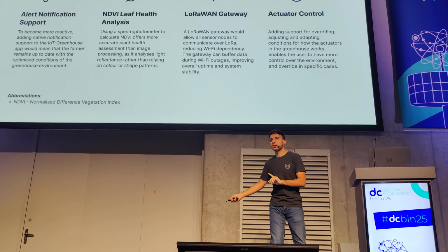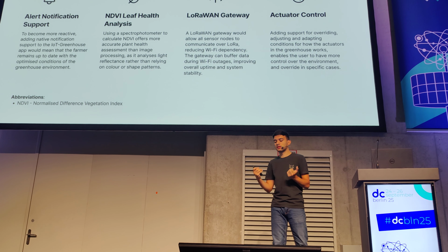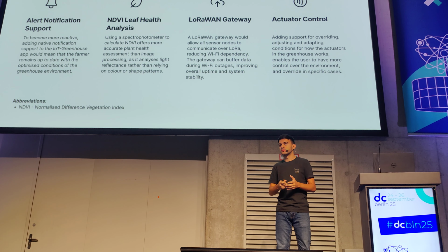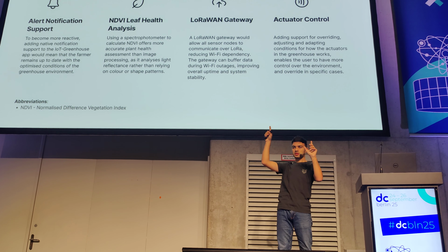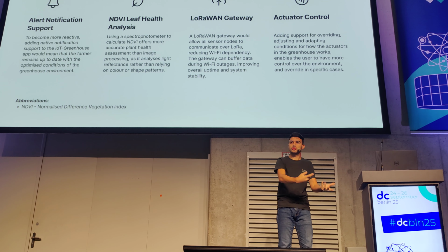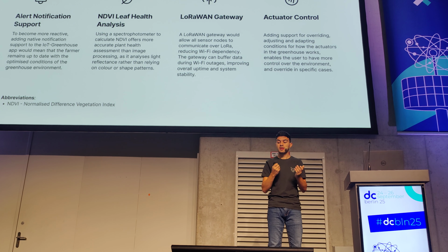Once the internet comes back alive, it will also publish that on the web. At the same time, the LoRaWAN gateway will give us a way to scale larger systems. So all the ESP32s will connect to one point, and then at one point, we'll make a push to the API server and then on the website infrastructure.